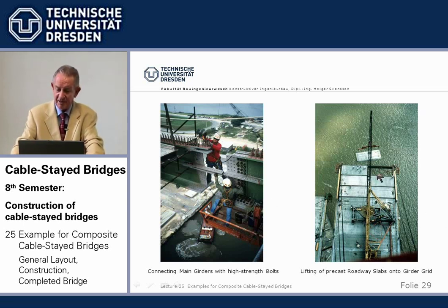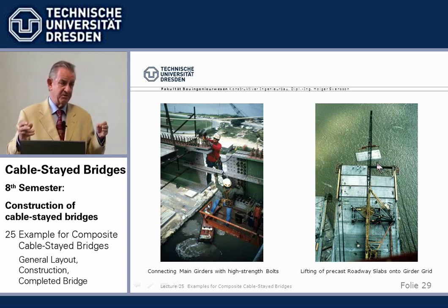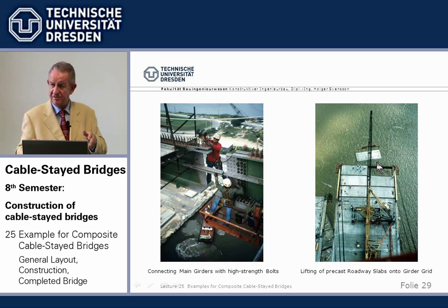Now, after the steel grid is installed, we then transport the deck up with the same derricks. We had the basic consideration: do we want cast in place or do we want precast? And we had offered both in our tender documents, but the contractor decided he wanted to do it, as you say, on site, piecemeal in small pieces, and then accept the joints, which are of course the shortcoming. On the other hand, shrinkage and creep is less. So this is a good method.